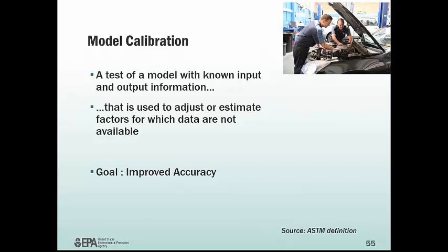So we're diagnosing problems, much like a car mechanic. We're reassessing all the initial assumptions we made. We're doing trial and error with many model runs. We're doing sensitivity analysis, where we're fixing all the model inputs and changing one input alone to see if it has a big influence on the outcome.